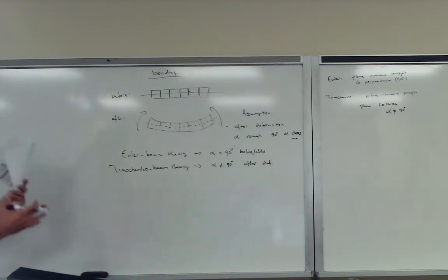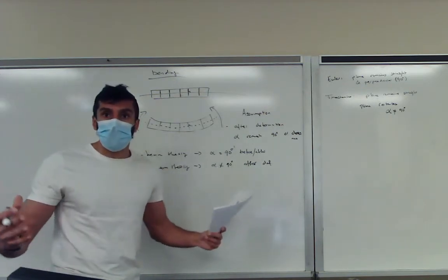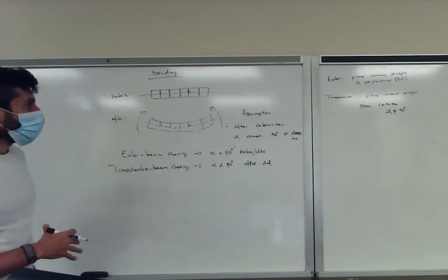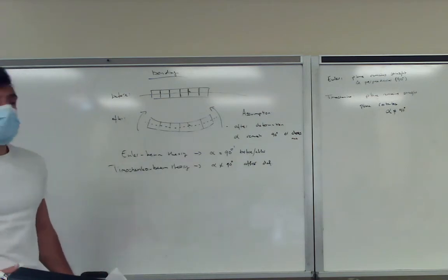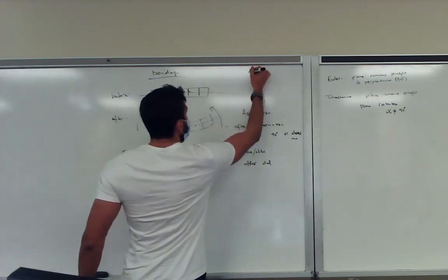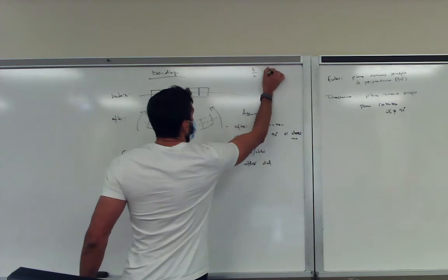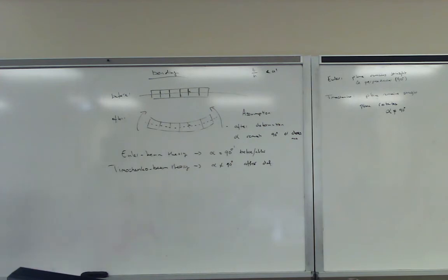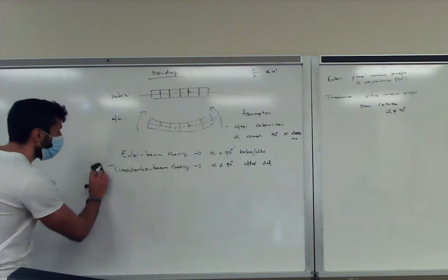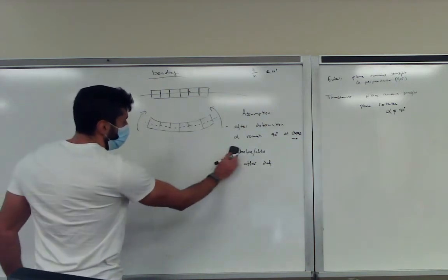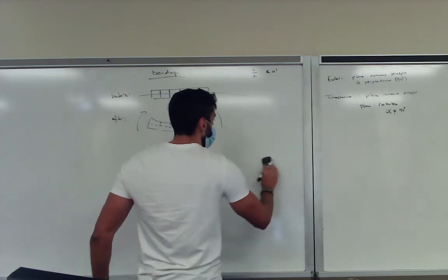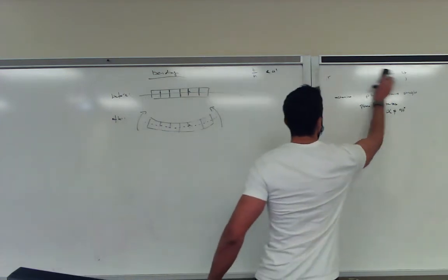Often, when the beam is short and very thick, we cannot ignore it, and when slender and long, we can ignore it. So similar to the thick wall and thin wall, we can come up with a ratio, if you remember, of thickness over height, which is less than 10%, 0.1, we can basically ignore it, and if it's a factor of just 2 or 3, then we cannot ignore it. In that case, we just assumed a factor of 10. In this case, we can use a slightly more fundamental or scientific method to determine it.